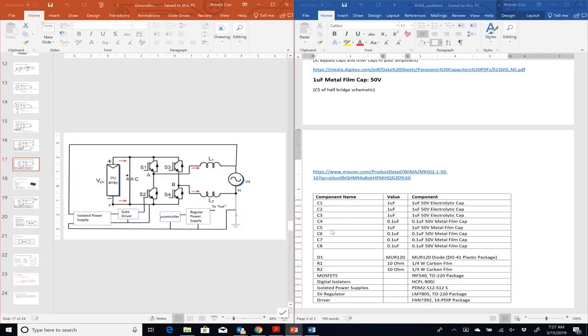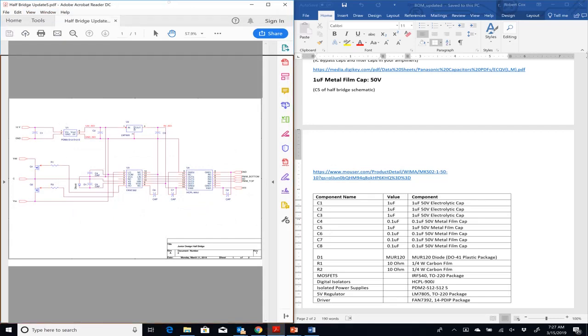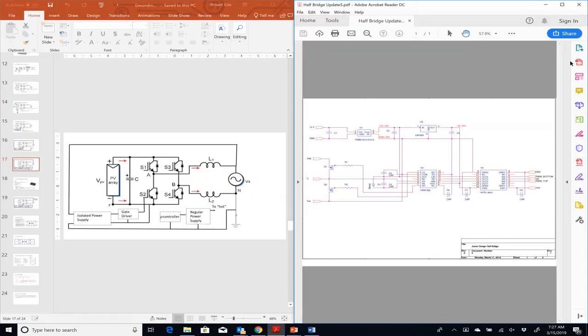So the actual schematic that we used was this, okay? This 12 volt input here, so the isolated power supply isn't powered directly from the grid like it's shown here, but it is powered from a grounded source, okay? So the isolated power supply is powered from a grounded source. Its output is listed as ground ISO and 12 ISO, or the net names, right? So this would be 12 ISO, this would be ground ISO, right?